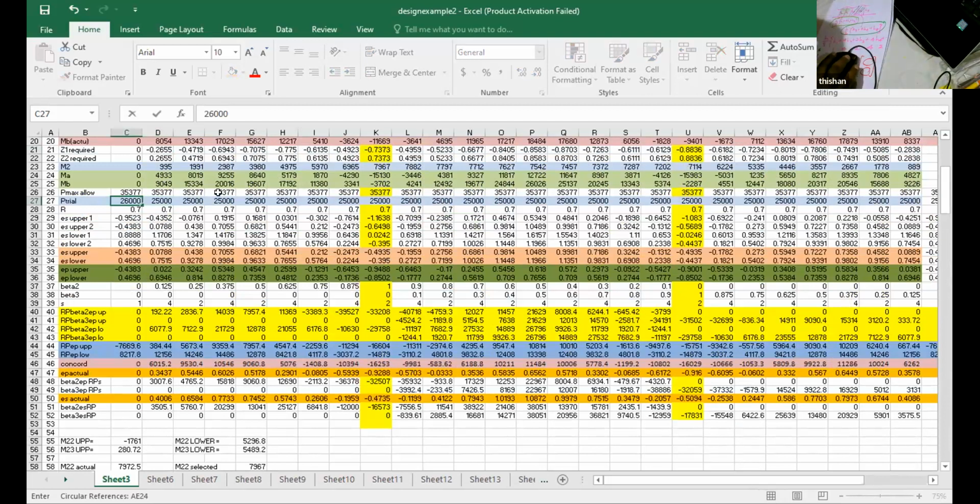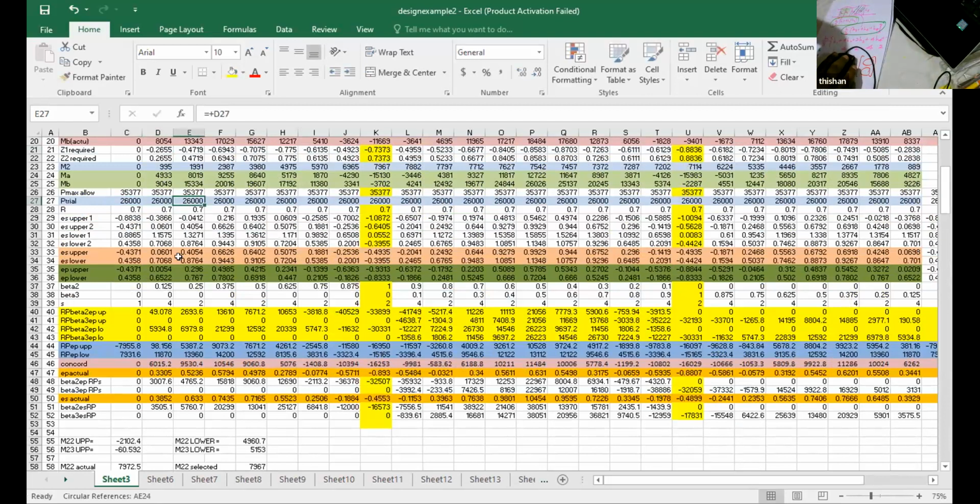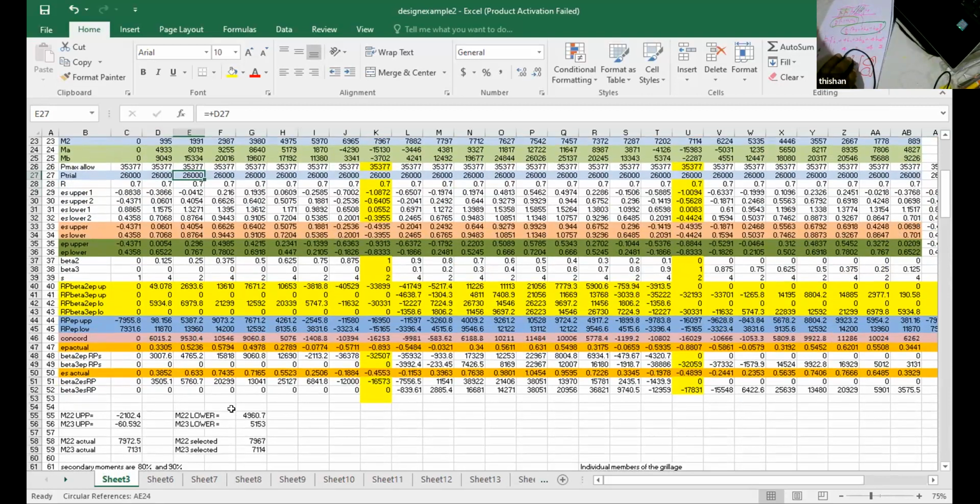What you have to keep in mind is, if you don't do this check, you might be chasing a set of limits in which you can never ever fit a bending moment diagram. To avoid this problem, when you are doing the calculation, while selecting the pre-stressing force, first we look at the graphics and see how much is needed.